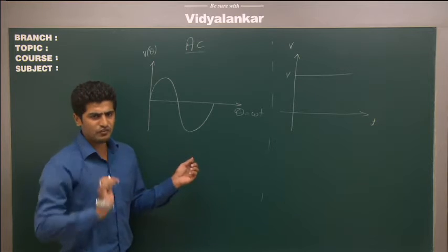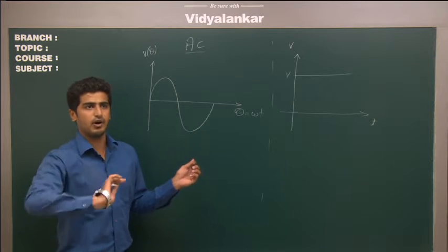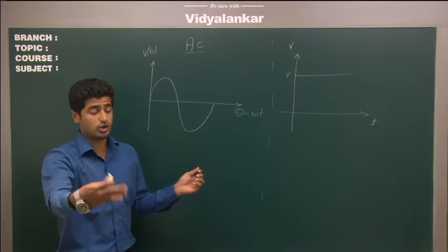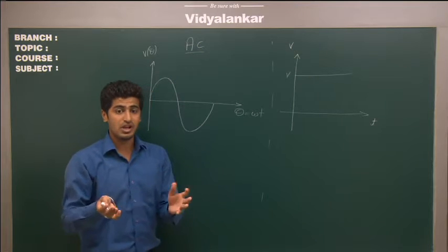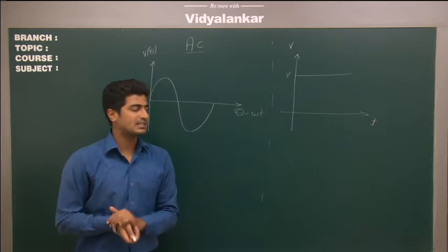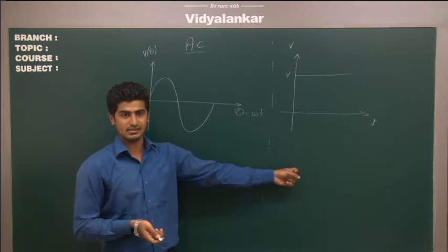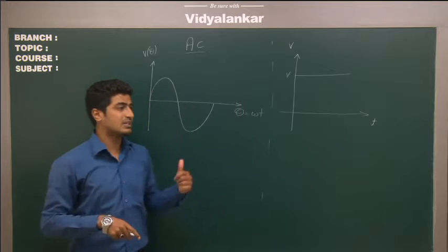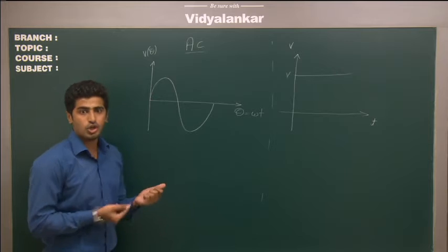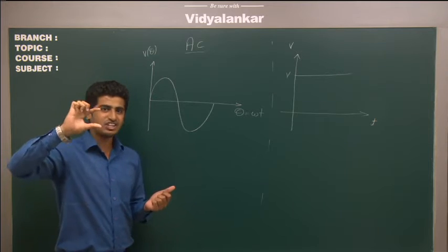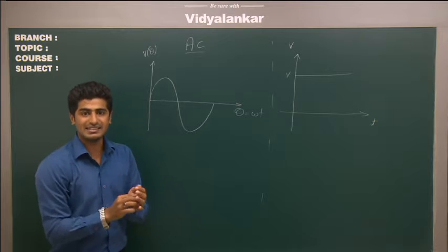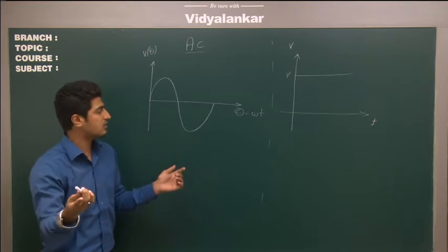And if I have to give a very simple example, let's say your mobile phones. Everybody uses mobile phones, correct? And a mobile phone requires a 6 volts DC supply to charge. This is a signal which looks like this. But eventually you will connect that to a source, which is basically your charger, and eventually the charger goes to your mobile phone. That charger is nothing but a circuit which converts an AC signal to a DC signal, precisely a rectifier circuit with a filter circuit.